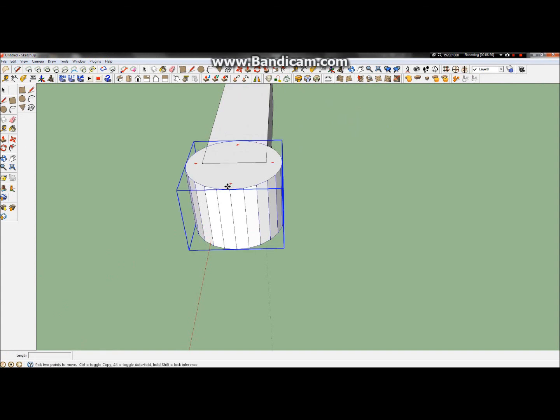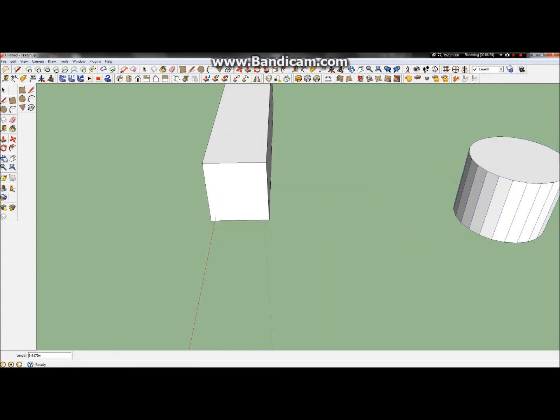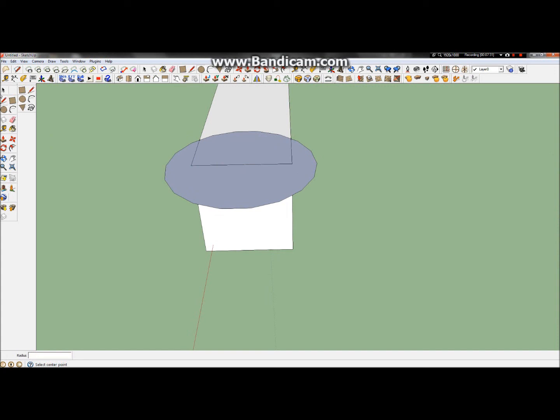Let's just move this one out of the way and try another one with a few less sides. Maybe 18 or something. Alright. We'll make the radius. Wait, first of all, we want to set the sides, so we'll say 18. Let me see if I remember how to do this. 18 S and say enter. There we go. Then we'll set the radius 1.65. Enter. Let's go ahead and flip that face so it's reversed.